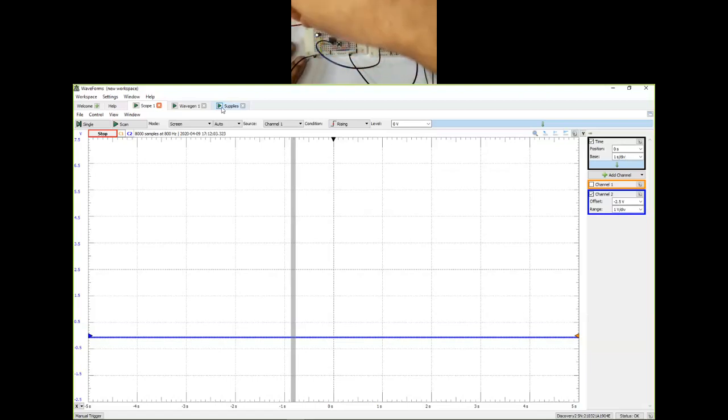And I can do that by simply placing another 1 microfarad capacitor in parallel with the 1 microfarad capacitor that is already present in my circuit. So right now, if I have R1 to be 100K and C1 to be 2 microfarad, then my output pulse duration is going to equal, theoretically, 220 milliseconds. So it has gone up from 110 to 220 milliseconds.